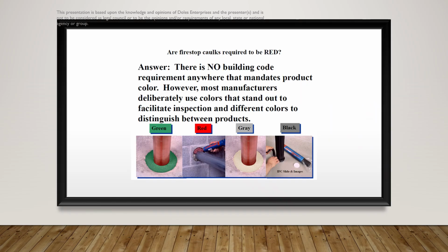Firestop materials can come in many different colors. Here are a few important rules to follow when it comes to the materials used in Firestop. Do not mix manufacturers' products in the same penetration. Mixing different brands of materials in the same penetration will void the fire rating of the UL or ASTM approved system. Whatever fire stopping method you employ, check to make sure that all materials and assemblies are approved by a nationally recognized testing facility for the specific type of Firestop to be installed. Never substitute approved materials with items such as mortar and concrete, expandable combustible foam, or other materials that cannot meet the required fire-resistant rating.